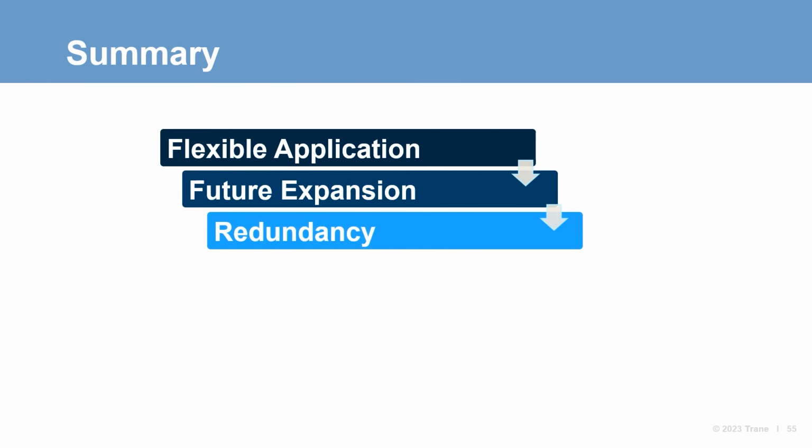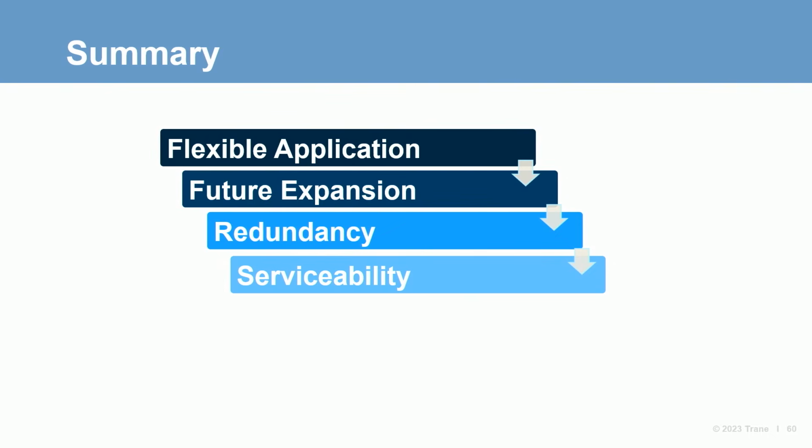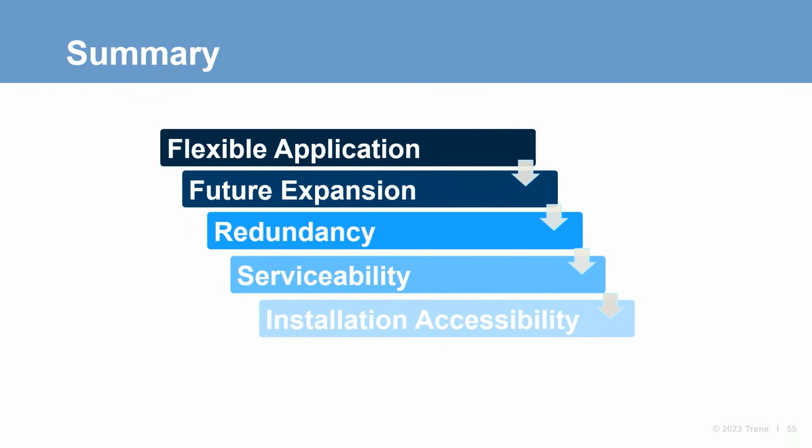Redundant capacity can be reduced because of modular chillers' smaller nature, and service follows suit because a module can be isolated from the system while the remaining units continue to condition system fluid. And in retrofit jobs where minimal construction is desired or accessibility is tight, their small size can make installation faster and less intrusive to building occupants, all while keeping compliance with standards in mind.